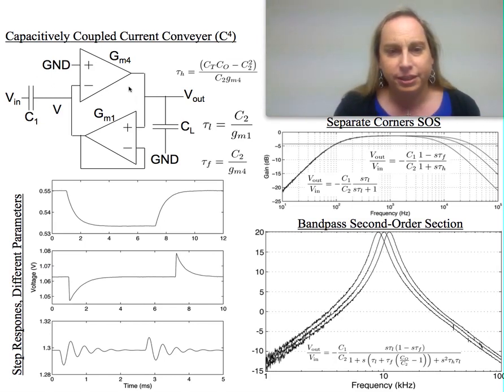One of the typical ways to look at this is as separated corners, where you have really wide spacing and a very nice, good band region. Typically this band region is a question of what the gain is in terms of the capacitor. This was a particular structure where the gain was set pretty close to 1, a little less than 1. And so you get a very nice response that looks like 20 dB per decade on this side, rolls into a corner, has multiple orders of magnitude for your passband, and then rolls off on the other side. So you actually do get a nice high pass response and an almost separated low pass response.